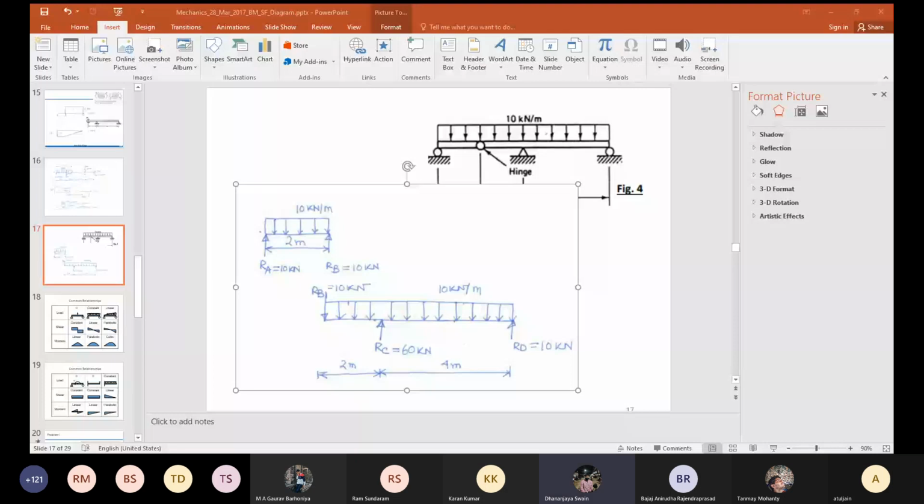You get the y direction reaction: RA plus RB plus RC equals something, 10 into 8. Oh, one equation. Yes, sir. Then you conserve moment about RB. Two equations. Conserve moment about RA. But the three equations that you write are not linearly independent. You only have two independent equations.